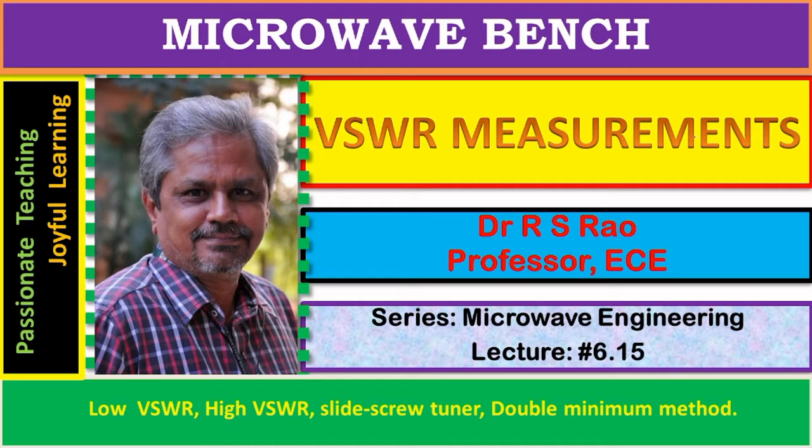SWR can be measured with a microwave bench. In the measurement process with the microwave bench, first a standing wave has to be established over the slotted section of the bench. It is established by connecting a mismatched load to the bench. Depending upon the amount of mismatch, a standing wave pattern with a certain value of VSWR comes into being.